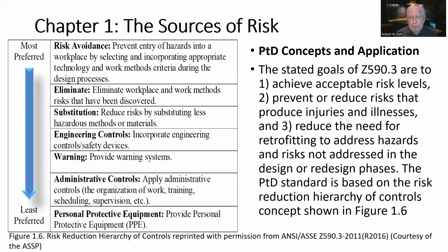Okay. So the stated goals are to achieve acceptable risk levels, prevent or reduce risks that produce injuries and illness, and reduce the need for retrofitting to address hazards and risks not addressed in the design or redesign phases. The PTD standard is based on the risk reduction hierarchy of controls concept shown in figure 1.6.